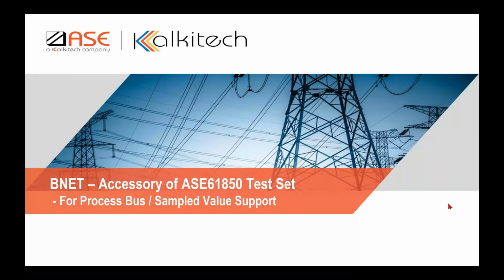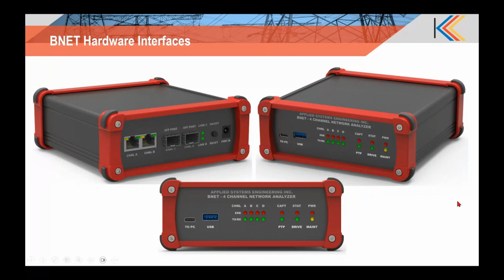And Larry, can you explain about the hardware to the audience so that they know what all capabilities come with it, from a hardware perspective? Certainly. The BNET hardware is slightly larger than the existing BCOM. The dimensions are roughly 6 inches by 6 inches by 2.5 inches. As you can see on the upper left image, there are two GigE Ethernet ports, and there are two SFP fiber ports for process bus sampling and network testing.